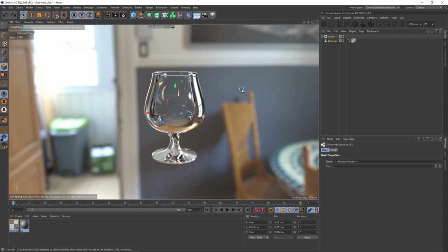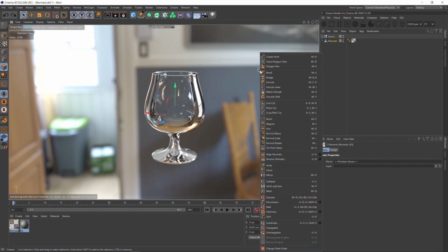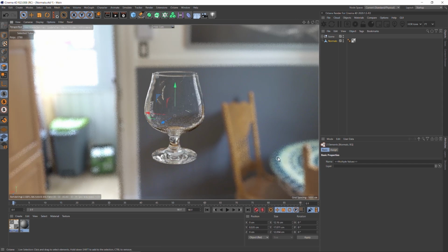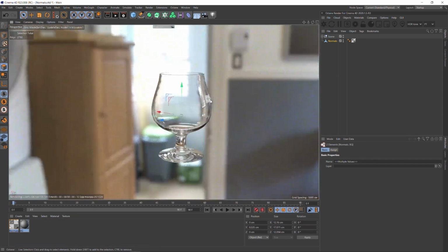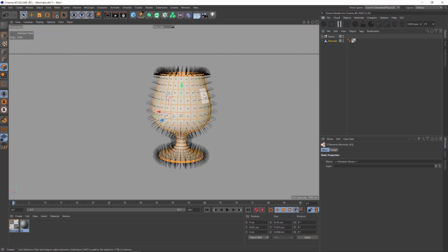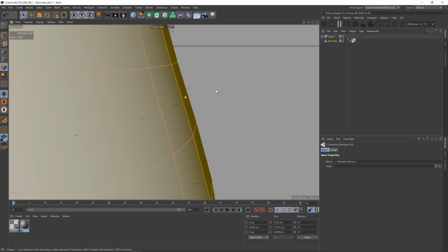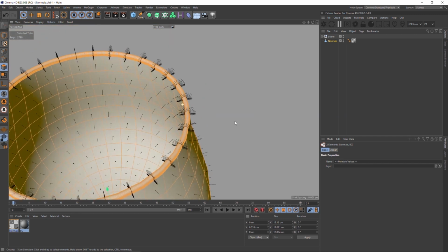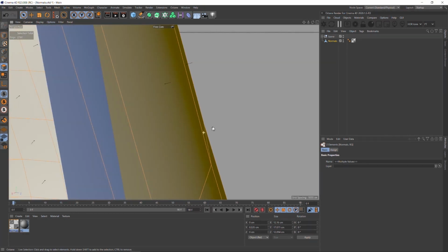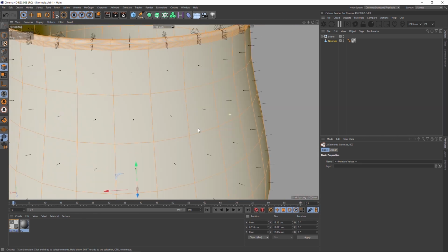So I know I have my polygon selected. So I'm just going to right click while the render's running and reverse these normals. Now you see we've got our shirt on the right way. Everything's facing correctly. Let's go ahead and stop the render. And you can see our orange side of the polygons, the correct side, is facing outwards, and our volume is contained with all our blues facing inwards.